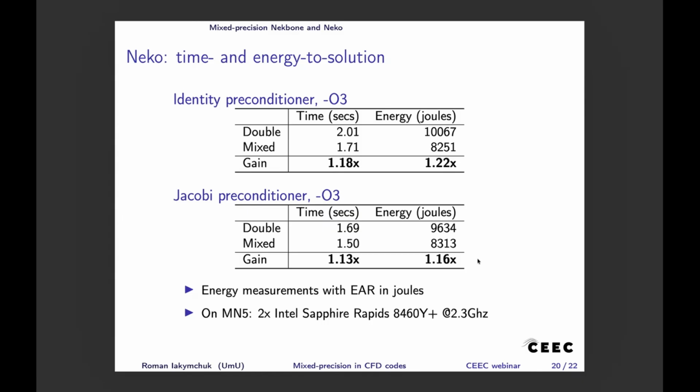Now we also have the pressure solver with GMRES, adaptive Schwarz multigrid preconditioned GMRES, and we have the whole complex, and we also mix precision, and we will see how it actually will perform in terms of gain and accuracy on the longer run, when time steps are activated as a full fluid solver.